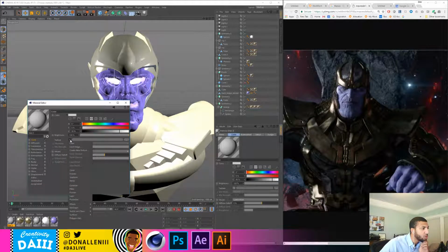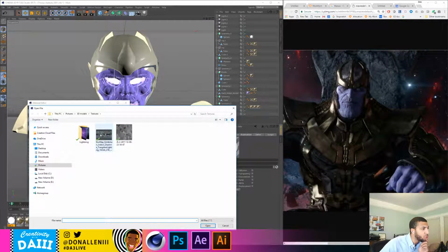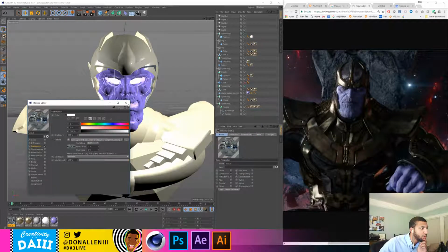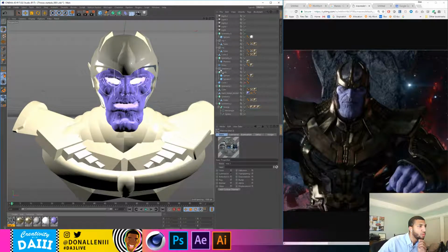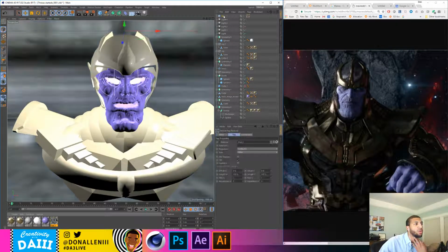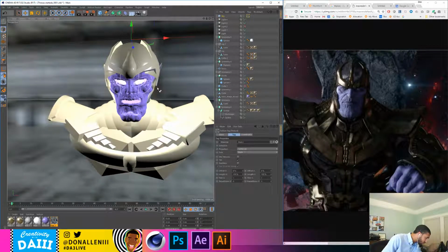Actually, we can do it as a luminance value. So go to luminance and load an image. I have this shiny environment I've used before to light my scenes. And we'll apply this as our sky. With this sky material, we'll get a lot more realistic reflections that will come out of the scene.